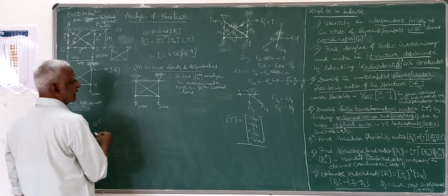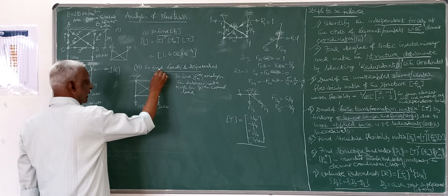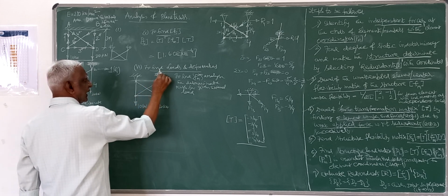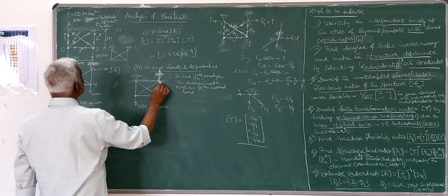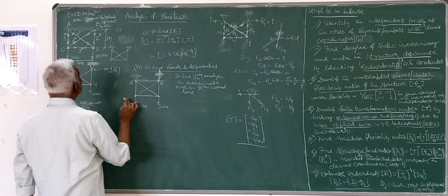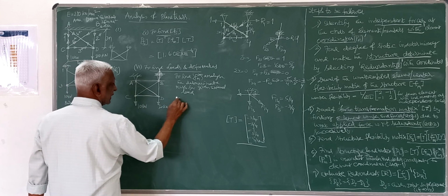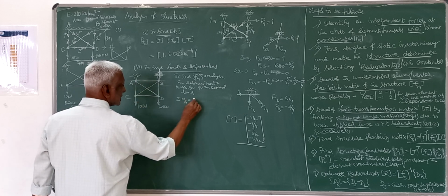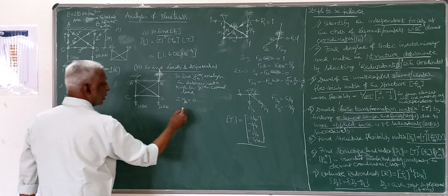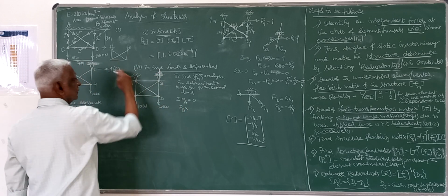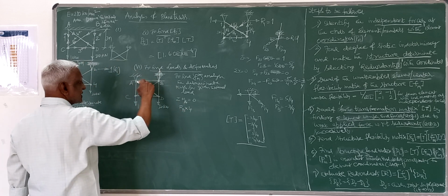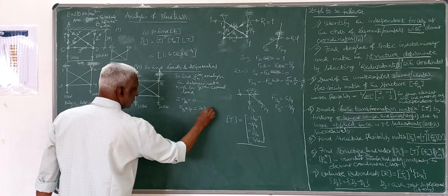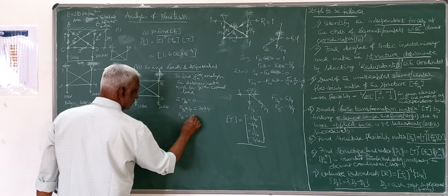So when you have 10 and 20 kilonewtons here, if I find the reactions, suppose I take it like this, this reaction is B, A, and this is C, D. If I take moment about C or moment about A as 0, then B into this 4, and this will not give any moment, only 20 kilonewtons into 4, so B will be equal to 20.